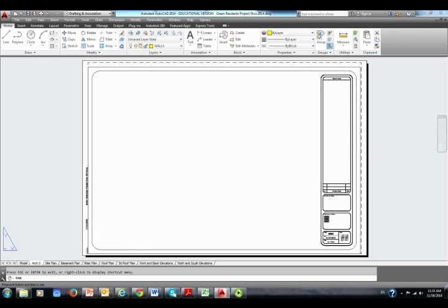He has site plan, basement, main, roof plan, 3D roof plan, front and back elevations, and north and south elevations. Today, after the due date, he will probably have another tab called house section. I would suggest that for your final, you do split elevations, because you can't fit all of the footing information, and the new addition should have information with regards to your design for the addition. Foundation walls and footings, and how you connect it to whether it's excavated, not excavated, and your wall section should also show the new construction that you propose there.